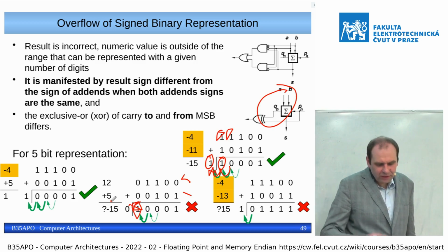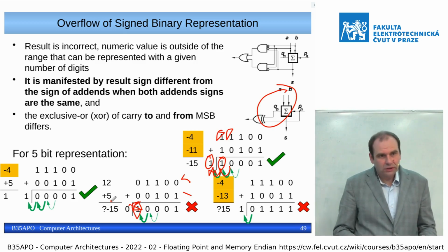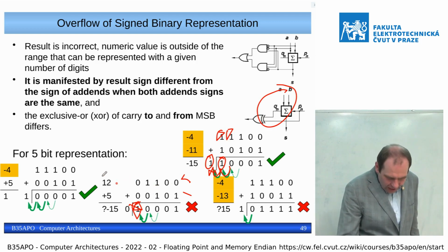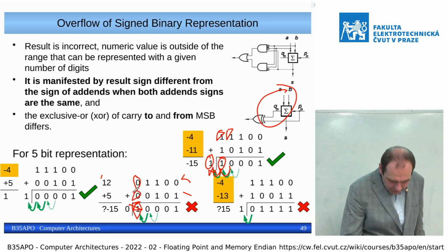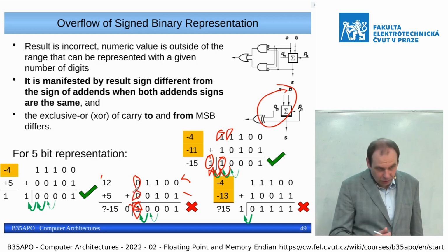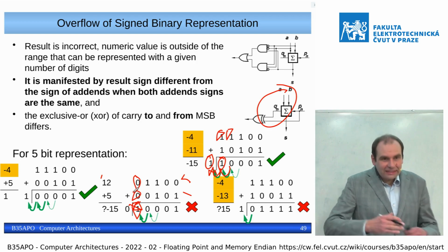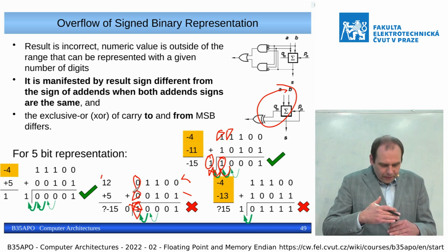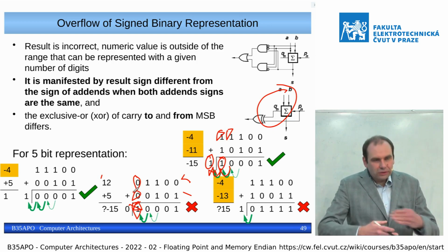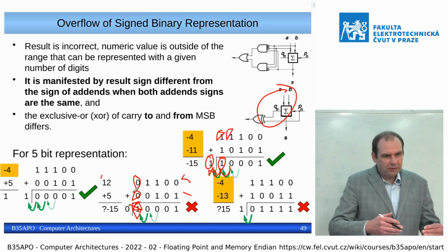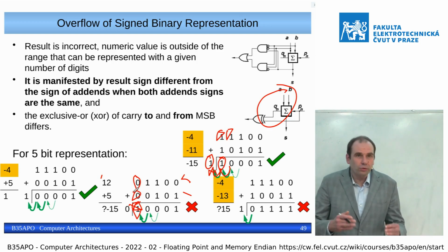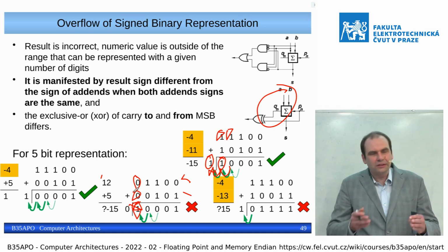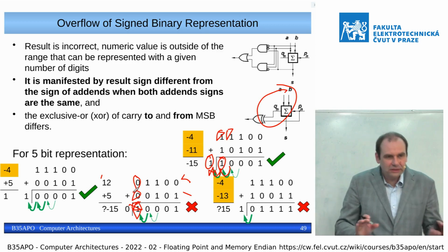So this means that we have overflow from the representation. It is the arithmetic overflow, because we have added two positive numbers. So both numbers have most significant bit 0. Okay. We add them as unsigned numbers, because we want to use the same hardware for the signed and unsigned arithmetic, even on some computers or on most computers. In fact, you do not have a different instruction to add and subtract signed and unsigned numbers. It is the same instruction.